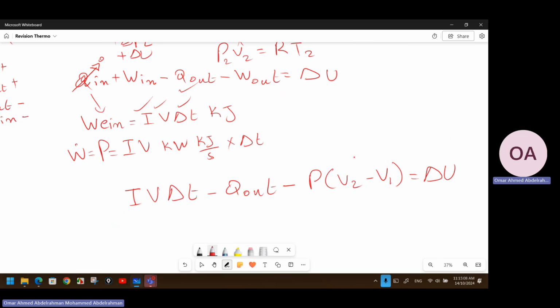You know from chapter 3 that the enthalpy is equal to U plus PV. Any system or any particles, gas, or liquid have internal energy. This internal energy, when it moves, will move due to flow work, which is PV, because of a pressure that will move a volume of the liquid or the gas a certain distance. Okay, so that is the enthalpy.